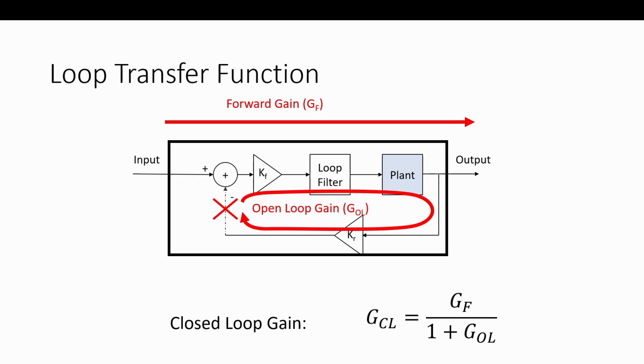It could be a simple amplifier with a gain of 10 and the forward gain would be 10. But it could have a frequency and phase response. That's right. If any of those blocks in the forward gain path have an S if it's continuous or a Z in them, then it's frequency dependent, and then we have to be careful. And if I was modeling that system down in the lab, I would look at things like the step response to get that temporal relationship.